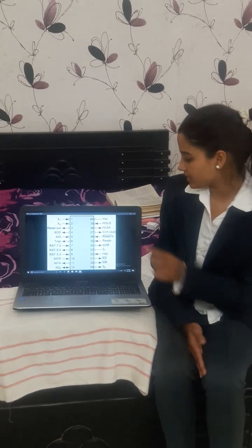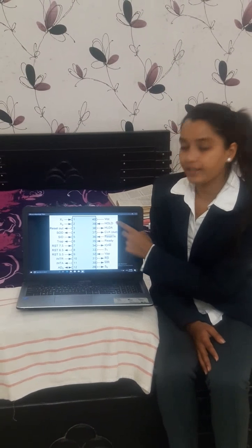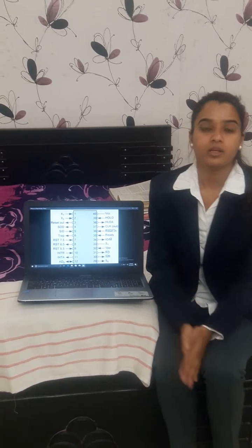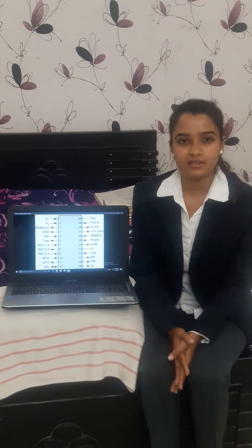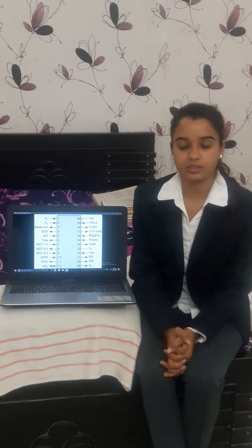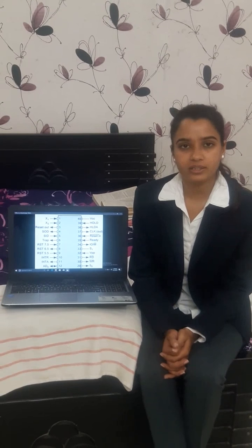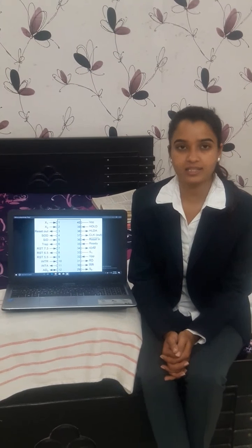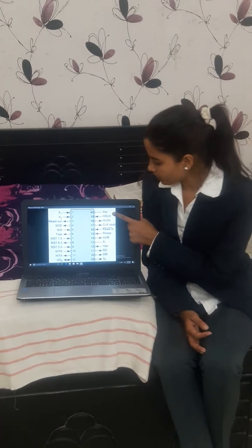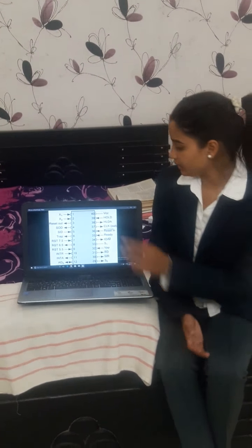The next two pins are pin number 38 and 39. Pin number 39 is HOLD and pin number 38 is HLDA. Data transfer between input output and the memory involves the microprocessor. This may slow down the speed of the microprocessor. To avoid this, the direct memory access, that is DMA, process is used. DMA has two signals, HOLD and HLDA. With HOLD,